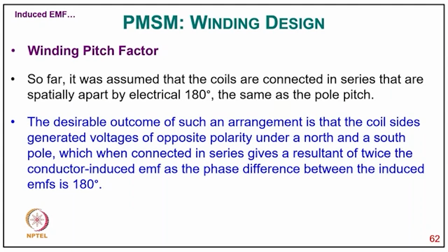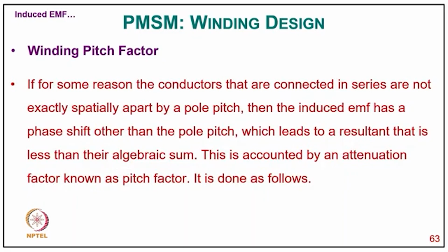So far, another factor is the winding pitch factor. So far it was assumed that the coils connected in series are spatially apart by electrical 180 degrees, the same as the pole pitch. The desirable outcome of such an arrangement is that the coil sides generate voltages of opposite polarity under a north and south pole, which when connected in series give a resultant of twice the conductor induced EMF, as the phase difference between the induced EMFs is 180 degrees.